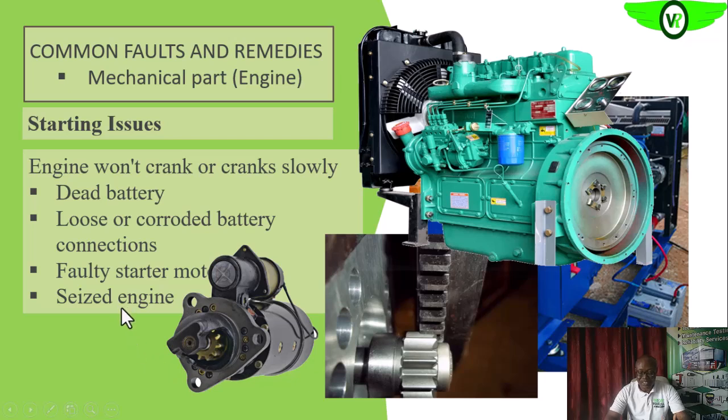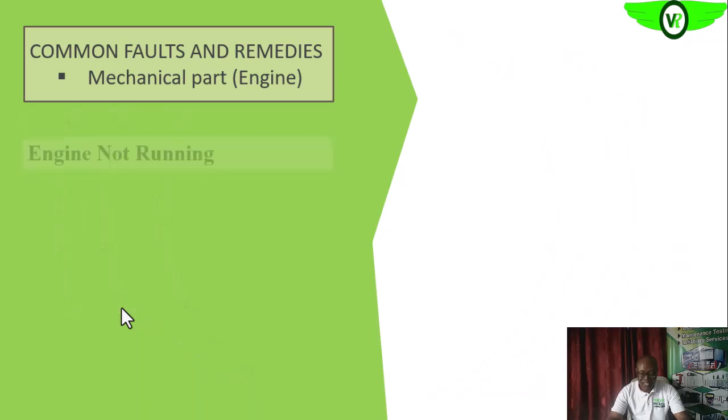If the engine is seizing, you need to check what is actually causing that seizure. And if it is something that is minor, of course you rectify. If not, you decommission the equipment and open up the engine to find out what is actually causing that seizure.